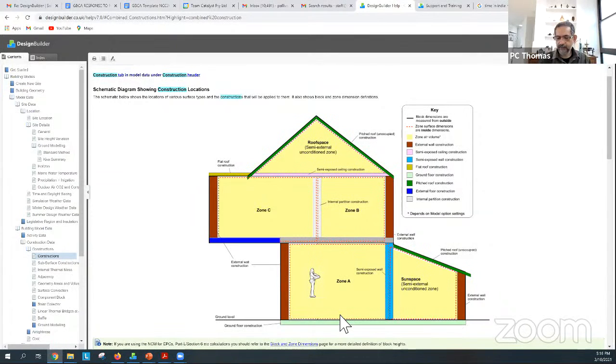And that's quite different from the rest of the model, because the ground temperature, or the deep ground temperature as we sometimes call it, doesn't change a lot during the year. Now, between summer and winter, there might be a 3 or 4 degree change across the entire year. It will change very slowly. There'll be a big phase lag between it. So, you know, the summer temperature will actually reflect in the winter, or at least partway through, 2 or 3 months phase delayed. And therefore the heat transfer that's happening is quite a different kind of heat transfer.